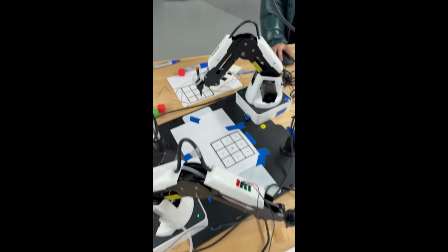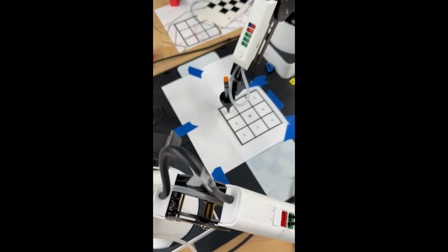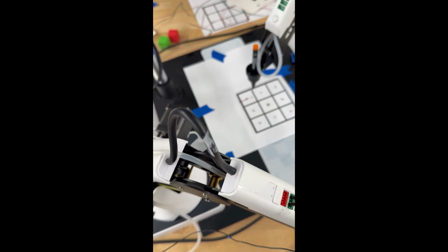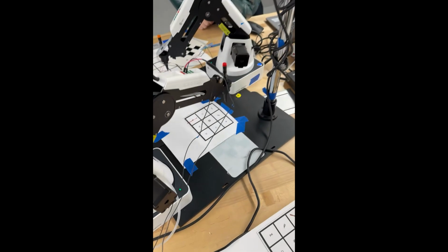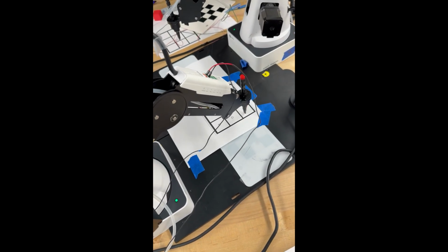It would recognize one of these 9 boards and mark the camera image coordinates of the center. Then, using a calibration file, the robot would convert these image coordinates to physical coordinates for the robot arm to move to. The robot then uses a move point command to reach the center of the chosen square.